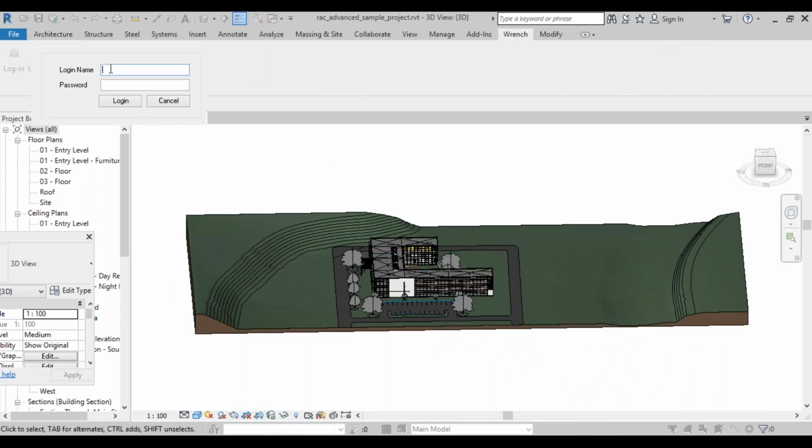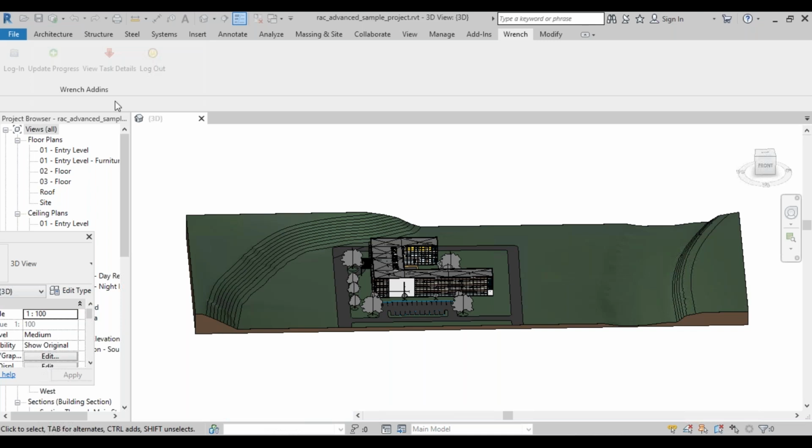I can have the updated status within here, and the system will show you in different colors on your 3D model that today's work that needs to be done is this on the model. And if I have anything delayed, I can show that in different colors. What is today's activity is shown in green, and what is shown in red shows that something is delayed, and that can be updated.